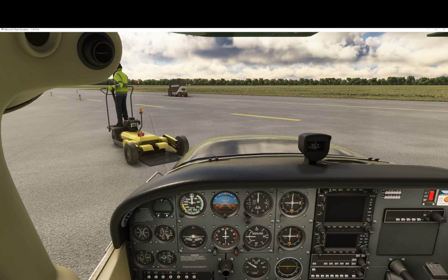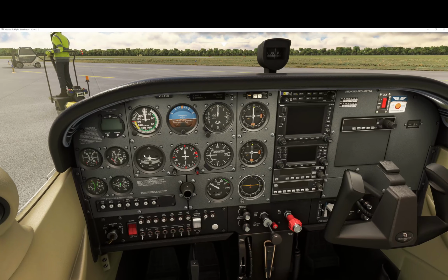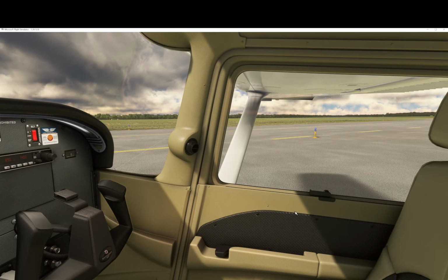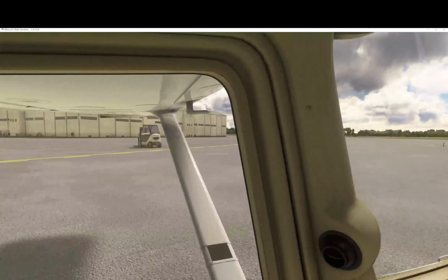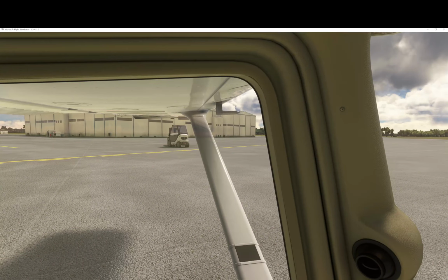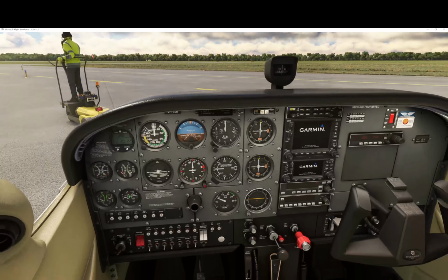So we've got a good start, and the engine is started now. Turn the avionics on. I'm going to lean out the mixture a little bit. Pull my RPMs back down to around 900. Okay, I'm going to throw my nav light on. And I'm going to bring my flaps back up. And the flaps are all back up now, so that's good.